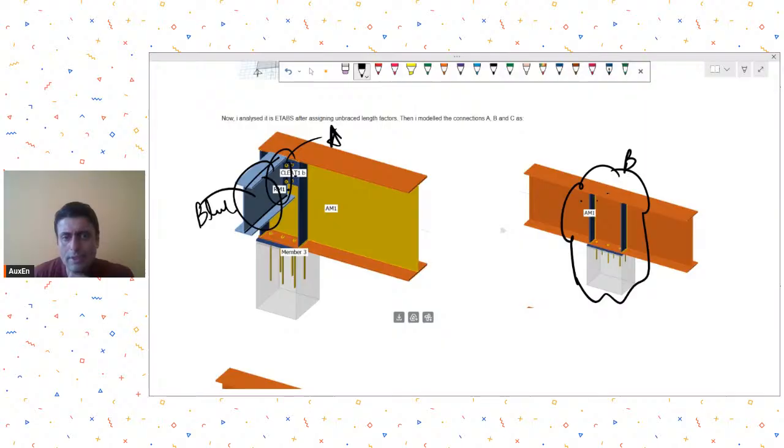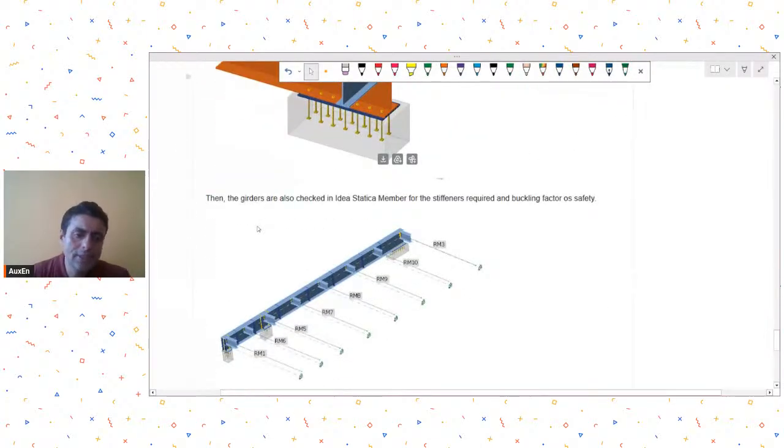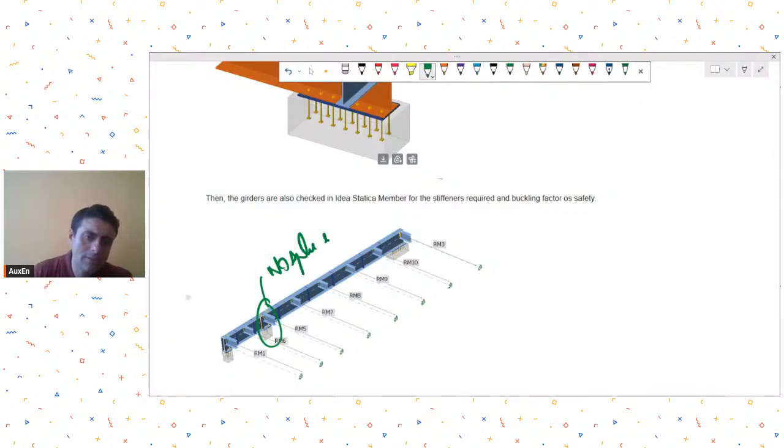So he has provided it something like this. Now here I have one observation: if you are going to provide it like this, ensure that there is no joint that you make over here. I'm assuming that if you were to make any splices, you will provide no splice in this region. No splice in this region. Okay, understood? So your member should go continuous.